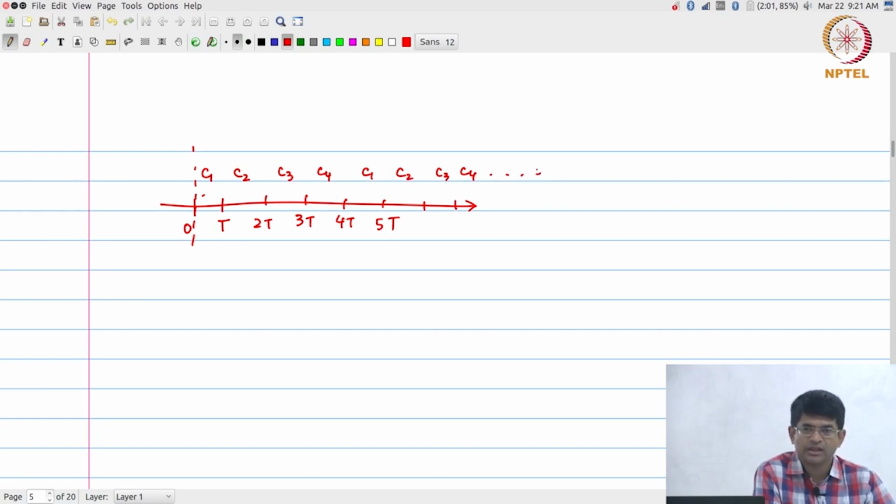There is another term that is usually used for this kind of allotment. What is it? Round robin. Okay? So this is the so-called round robin allotment. Essentially what it is saying is that all the masters that could potentially be asking for the bus, I will allocate a static time slot for them. Okay? Now this is great because effectively what it means is that every master is guaranteed a certain fraction of the bus, in this case 1/4 of the bus.